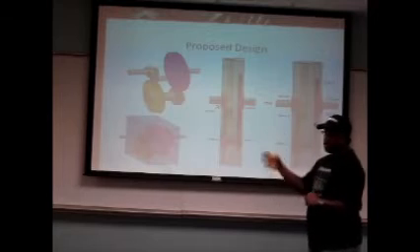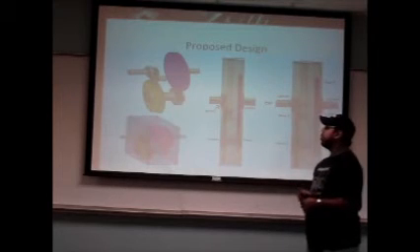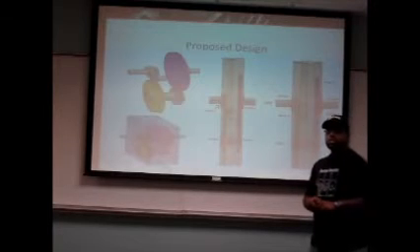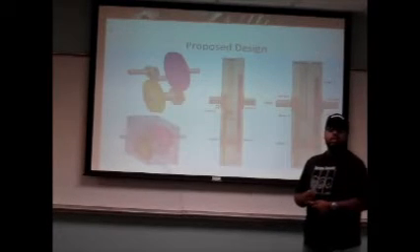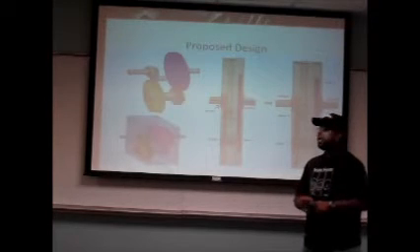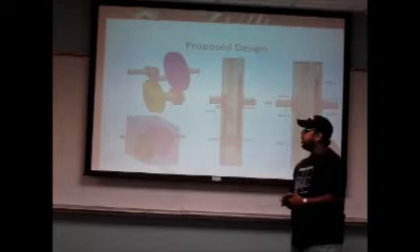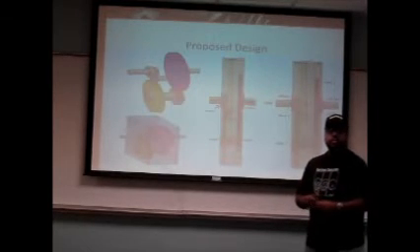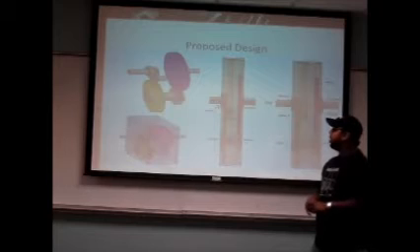Here is our 5-gear model with 5 bearings on 4 shafts. As you can see, gear 1 drives gear 2. Gear 2 functions as the idler to change the input that is clockwise into an output which is counterclockwise. Gear 3 is much larger than gear 1 and 2, which contributes to the reduction.